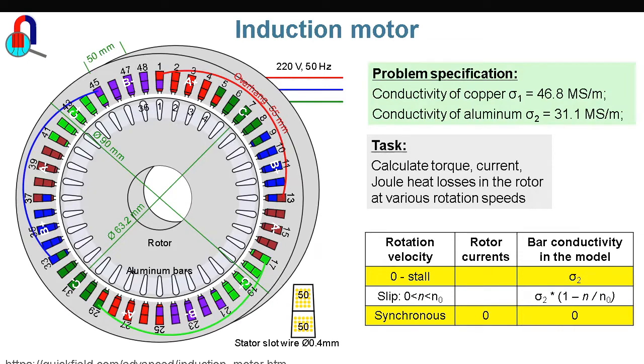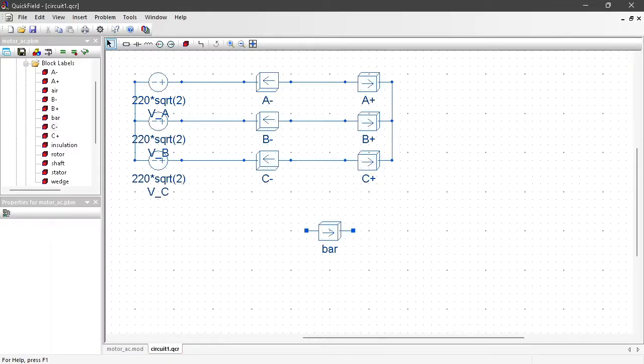You can find the calculation details on the example web page. Here I will present you with the result. The overhang resistance is 50 ohms per each phase. So here, back in QuickField in electric circuit, I will add the resistors. Here, and here, and here.